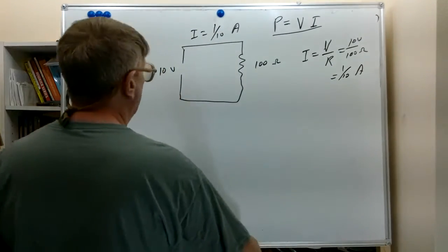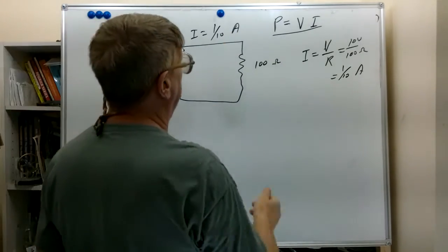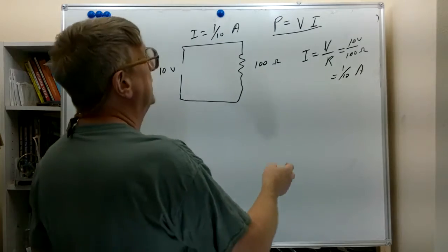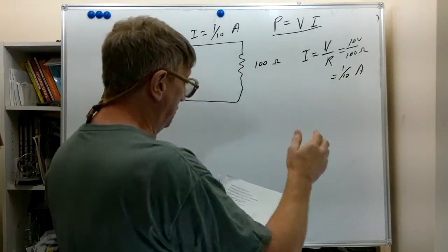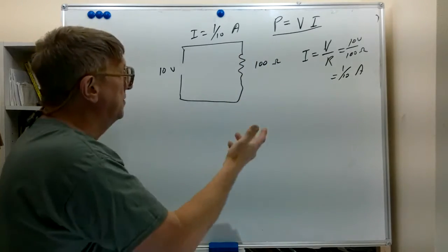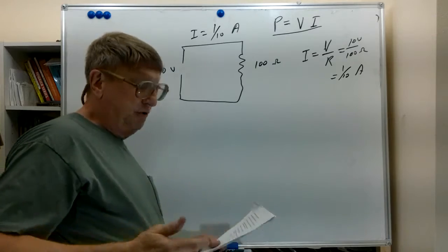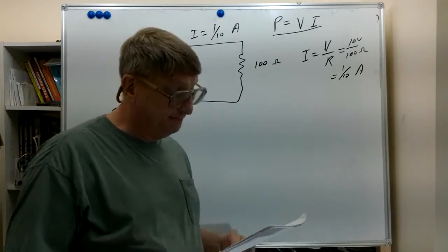So back to the 1 watt that we're drawing here, because we have a tenth of an amp times 10 volts. We have 1 watt of power being consumed. If we do that for 1 second, we will produce enough heat, which will be dissipated out of this resistor. We use it to warm the resistor, and then it'll escape into the air, equal to 0.24 calories of heat.